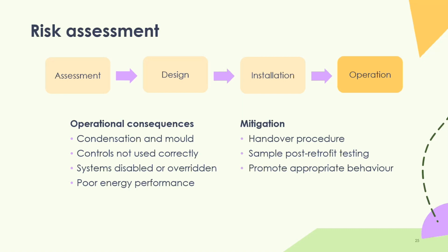And then poor energy performance. So think about carrying out sample post retrofit testing. Again, if you're looking at digitalization or innovation, it'd be good to consider installing some of those data loggers now, before you carry out any of the installations, just to monitor how the improvements have worked. And then also promoting appropriate behavior in how they use the property.